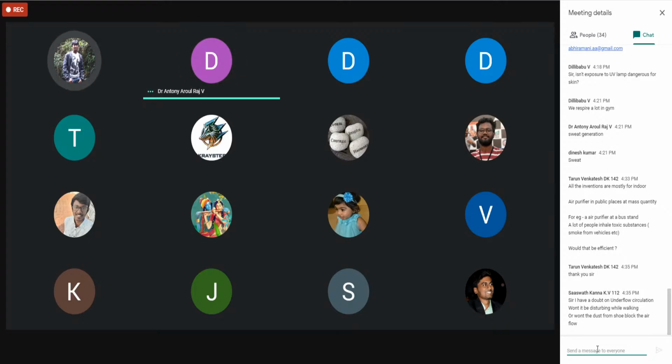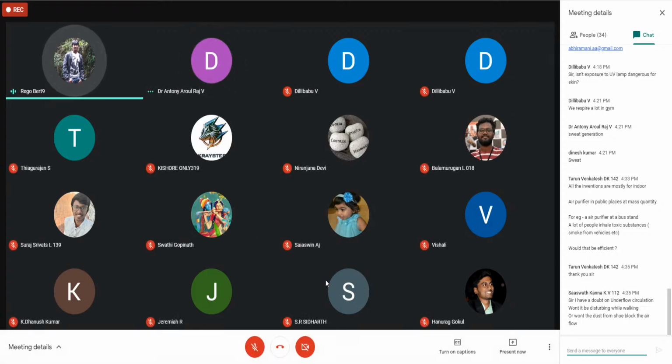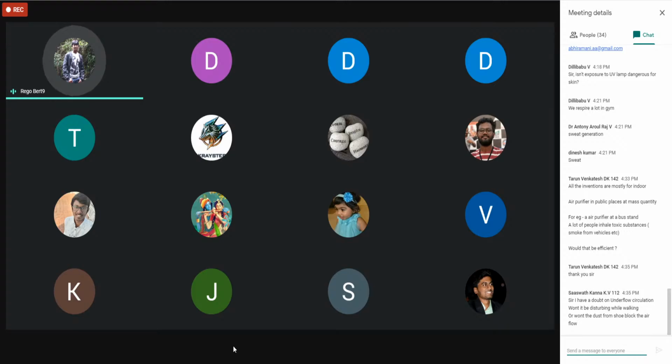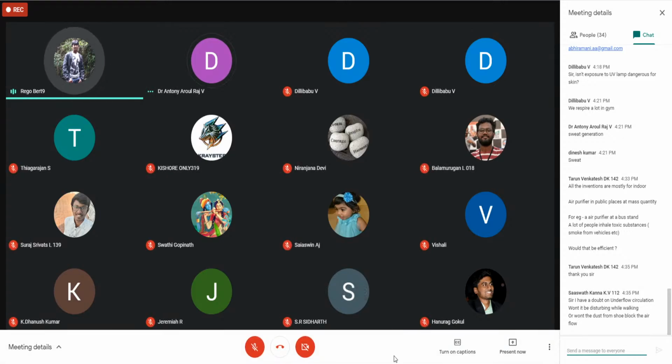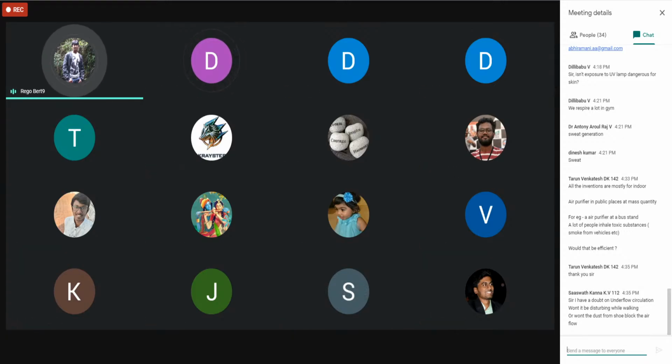system? Okay, understood, sir. Yes, you've rightly said. There will be multiple air terminals, sir. We will not give the air terminal in the corridor, because people continuously walk there. The air tile will be placed in such a manner, and moreover, if I'm taking air at 12 degrees Celsius and supplying 12-degree air from the floor, that is going to create a worst situation for the employees, because of the chill, they cannot sit in a 12-degree air supply.